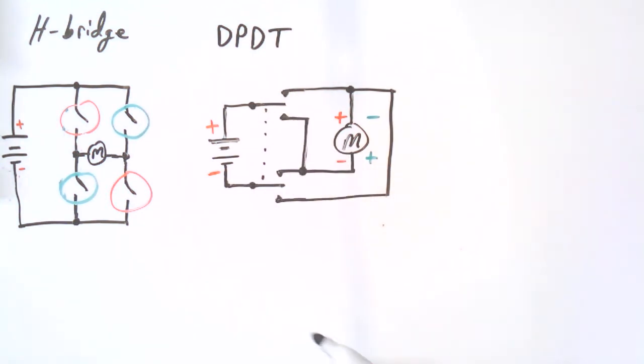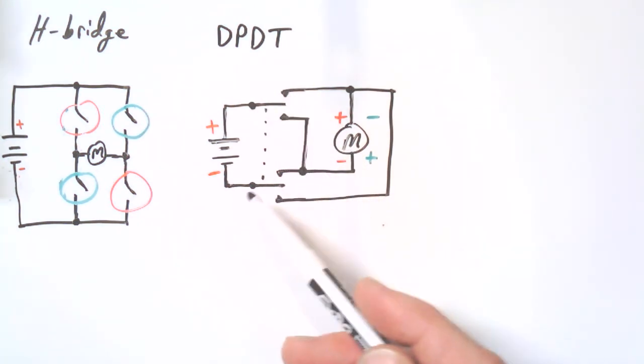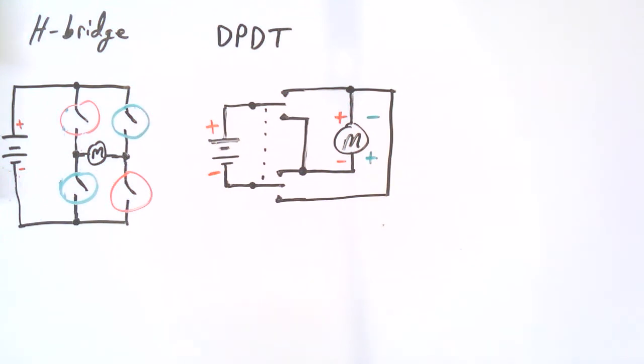And you can see exactly that you need to take the negative of the voltage source and connect it to, what did I say? That was A, B, C, D, E, F. Connect it to F, point F. And so you'd have everything defined and everything labeled. That's how it really happens in the real world. That way you can't be constantly going back. It opens up a real possibility of making a mistake, but it also just takes more time that way. It's actually faster to be meticulous with your drawing, and then it really speeds up the wiring time.